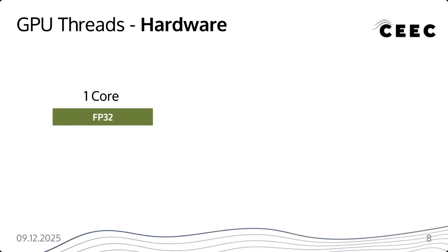So you'll see a lot in GPU hardware descriptions this idea of cores. And you see it also in CPUs. And this is the primary difference between CPUs and GPUs: CPUs have a few very complex cores that are used to do a few things at once, usually. And these things that the CPUs are doing are very complex, typically a lot of logic, a lot of data movement, a lot of stuff like that. GPUs are the flip side of this coin. GPUs are going to be doing many, many simple things concurrently. And this is reflected in the GPU hardware or GPU cores. The circuitry in them is much, much simpler.